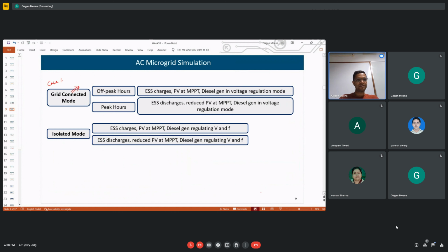We have two types of power quality issues. One is voltage related, the second is current related. In voltage related, we have voltage sag, voltage swell, and voltage interruption. In current related, we have harmonics, notches, transients, and unbalanced load. Harmonics have several adverse impacts on the power system. Even unbalance also has an impact.